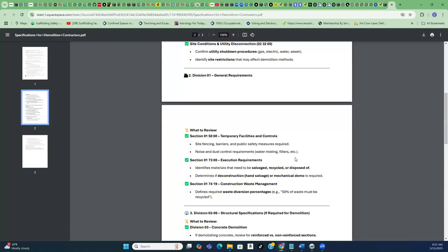They'll have it set up to where they'll show you where they want all of the additional spoils placed. So it's a good idea, especially if you're doing site demo, to really review the erosion plan, and we'll review that too. It's called the erosion plan, maybe in the South, but here in California, they've renamed it to the best practices plan.